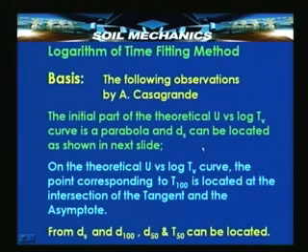So, we need to locate the starting point corresponding to ds, and we need to locate the point D100. Once we know the dial gauge reading corresponding to 0 and to 100, we can interpolate and find out the dial gauge reading corresponding to 50 and the corresponding time factor capital T50, and that is the method.